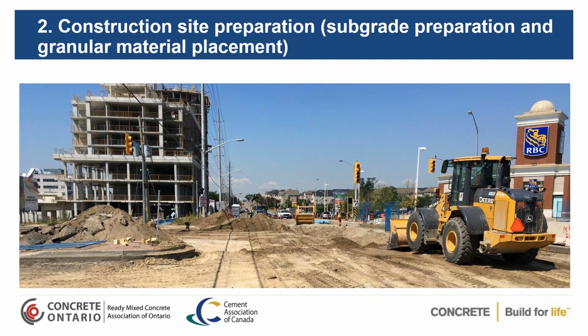So what we're going to first look at is site preparation. It's extremely important when you're doing a concrete pavement to have a uniform base. It doesn't matter whether you're uniformly strong or uniformly weak. If you have a base that's consistent, then you'll get your best performance. If you have different types of soils, what you're going to be doing is blending the soils and doing a transition so that you don't have an abrupt change in the strength.